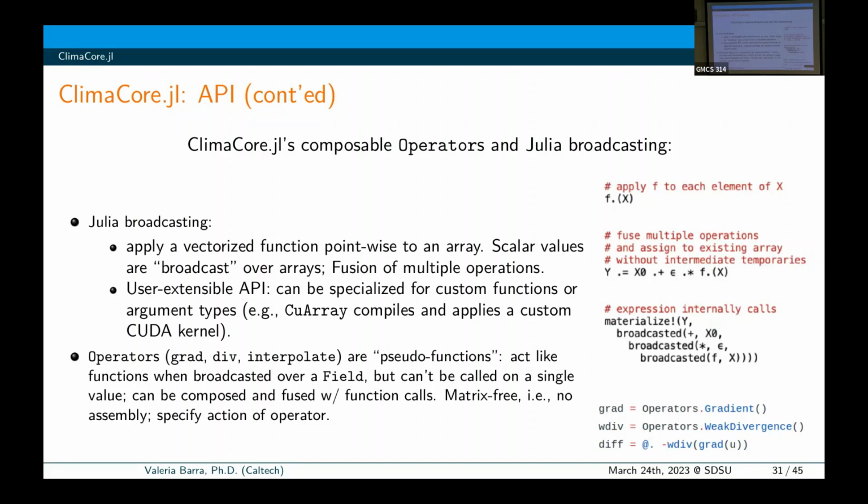For us, it really depends. Since we use this differential operator, you only assemble how big of a horizontal element you have. If we run with polynomial order 4, you have a 5 by 5. That's all you assemble, that's much for one element. We have different strategies for threading. For CPUs, we thread over horizontal elements, so we have batches of elements. And of course, you want to be careful because you also want to match register sizes.